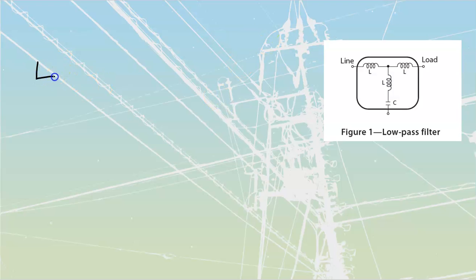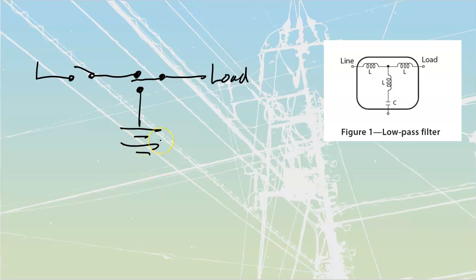But the basic difference is that a UPS is designed to feed through to my load. So it's almost the same as what we dealt with for transfer switches before, where we have a transfer switch inside of here. Here's my load. And then the UPS is going to maintain contact with my mains most of the time, and it's going to have a charging system. Okay, so it's going to be a battery-driven system over here that's charged off of that. It's going to have an inverter to come out of that. And so anytime that I lose power on my hydro end, it would switch over to this, and it would deliver from that battery system out to my load itself.